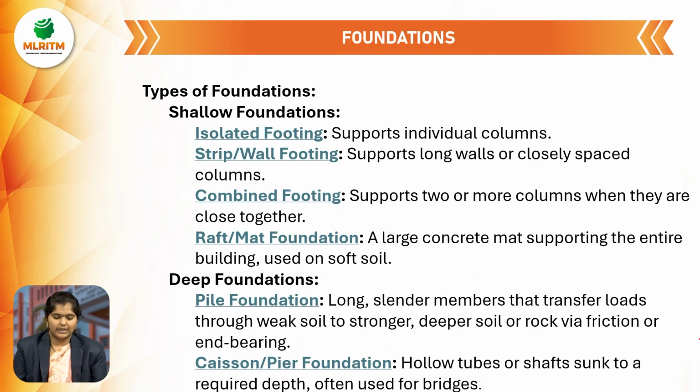So next, types of foundation. Shallow foundations are classified into 4 types of footings: isolated footing, strip footing, combined footing, raft or mat footing. Isolated footings support individual columns.